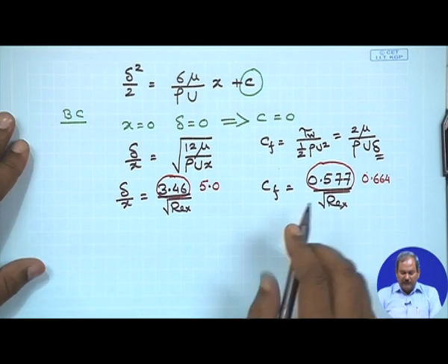So here you see that even with a very simple approach, the simplest possible velocity profile, you still are not too far off from the analytical result, which was obtained by solving a partial differential equation numerically to obtain the exact form of the boundary layer growth or that of Cf.